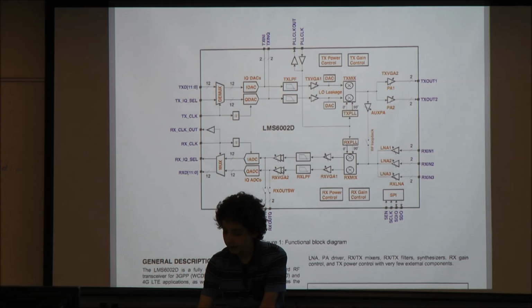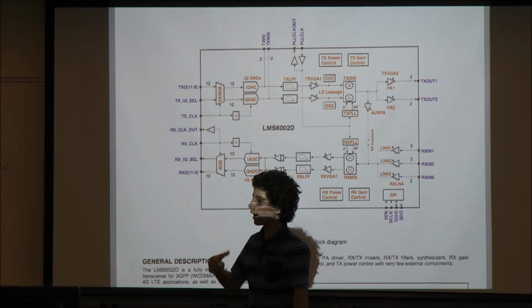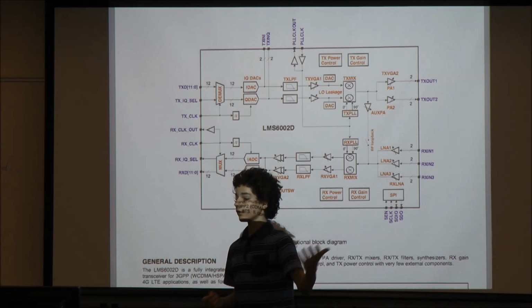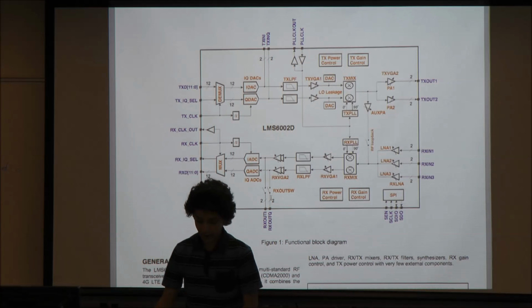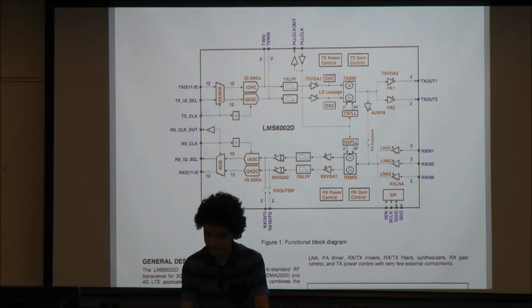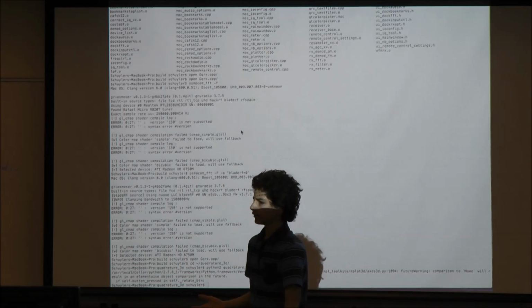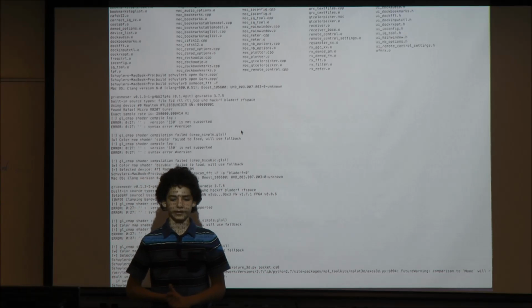Another amplifier, and you get these signals here. You can connect in your own IQ signal source if you want to, if you have a different mixer or stuff. That's connected to these headers on the BladeRF here. And then this goes out to the ADCs and stuff. So that's just that. There are other architectures. The PacRF uses a few different chips instead of one integrated solution.